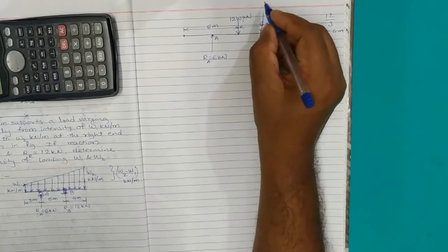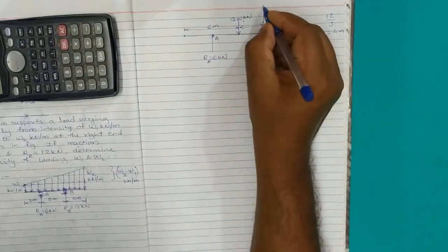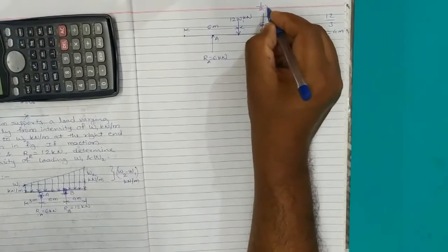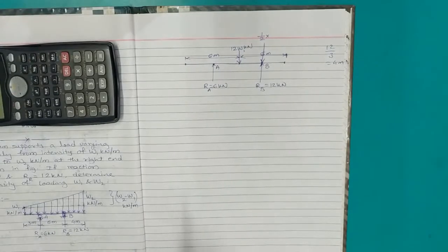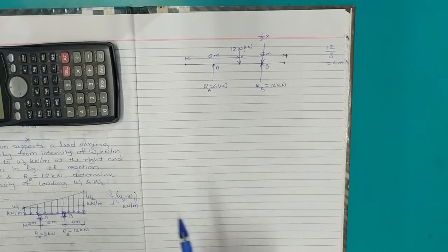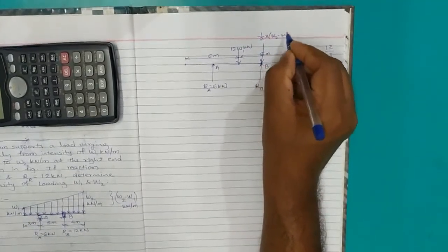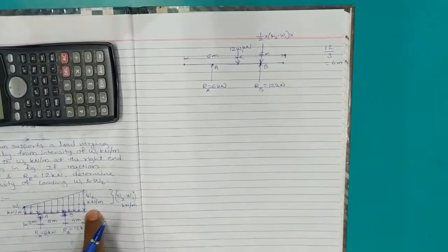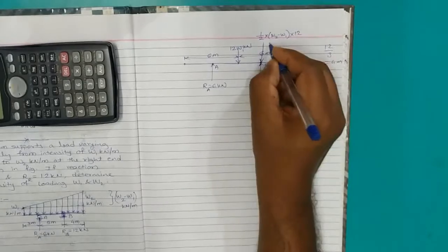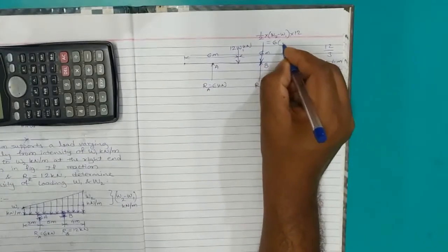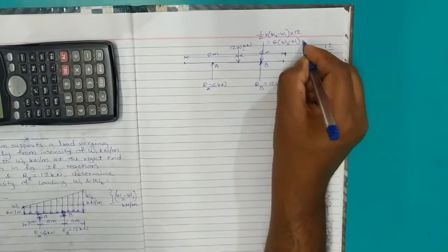And we know a triangular load is also called uniformly varying load. Area of the triangle is going to be the magnitude of the point load. Now area of the triangle is calculated as half into base into height. Height is, we said, W2 minus W1, into the total length of the beam itself as the base, which is 12. So that comes out to 6 into bracket W2 minus W1 in kilonewton.